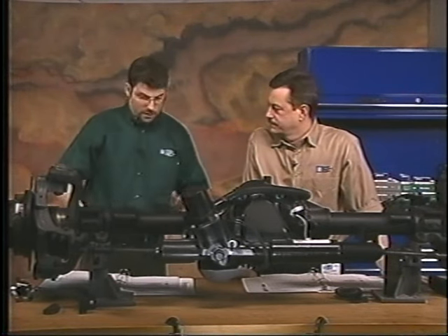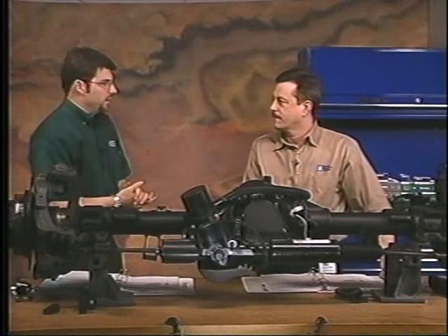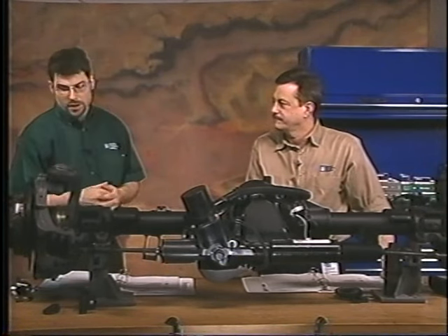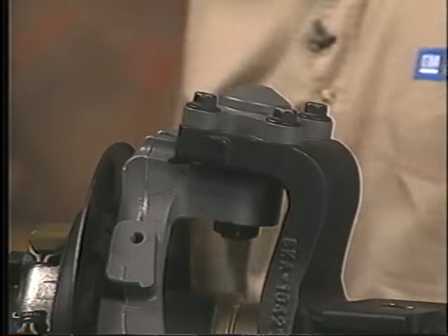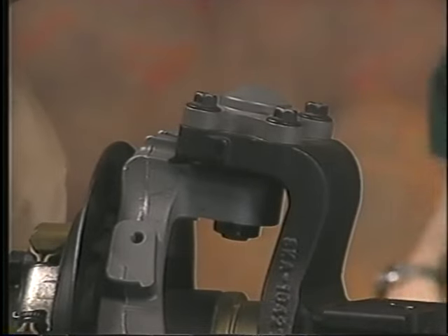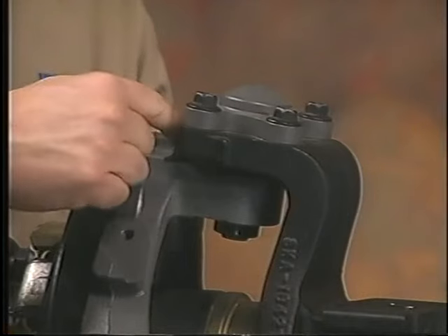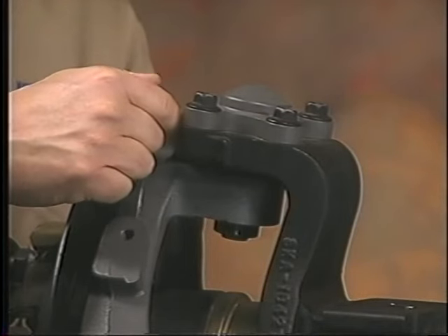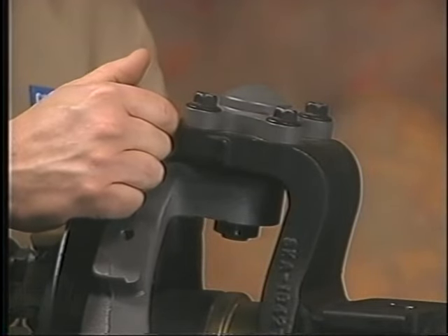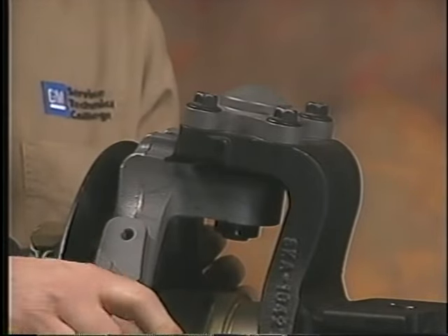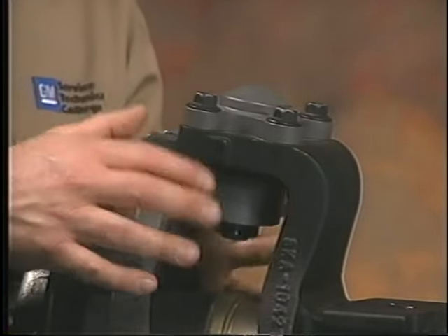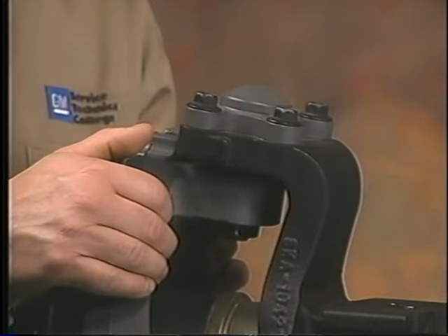Okay. Hey, Mike, got to talk about a couple more things here. We've got another piece of safety-related information here on our pinch point. Absolutely. Let's take a look at that. Now, this is kind of similar to front steering here. If these wheels are moved a little bit, we've got a straight-ahead position. There's a bit of room up here. You can get your finger in there, so it becomes a pinch point. If the wheels were to move a little bit, you know what? It's going to hurt. If we remove our tie rod, then this whole assembly could float a little bit on us. Okay? It could pinch, it would hurt.